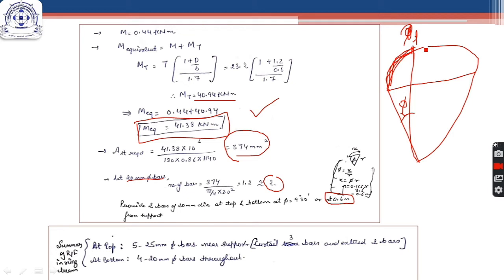So as this is an arc, you know from trigonometry that phi is equal to length of arc upon the radius, so L upon R. So R here is 3.6 meter for this particular beam, phi is 0.6166 radian, so L, that is the length of arc or the distance of this point from the support, we will get as 0.6 meter.